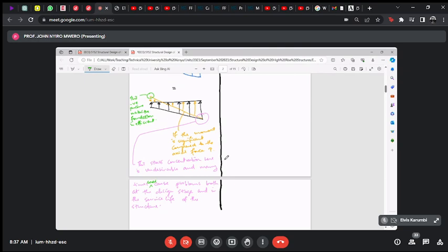But just a thought. When we do the foundation, we want to ensure that it doesn't exceed the safe ground bearing pressure. Usually where you have this stress concentration, there's a very high probability that the stress exceeds the safe ground bearing pressure.